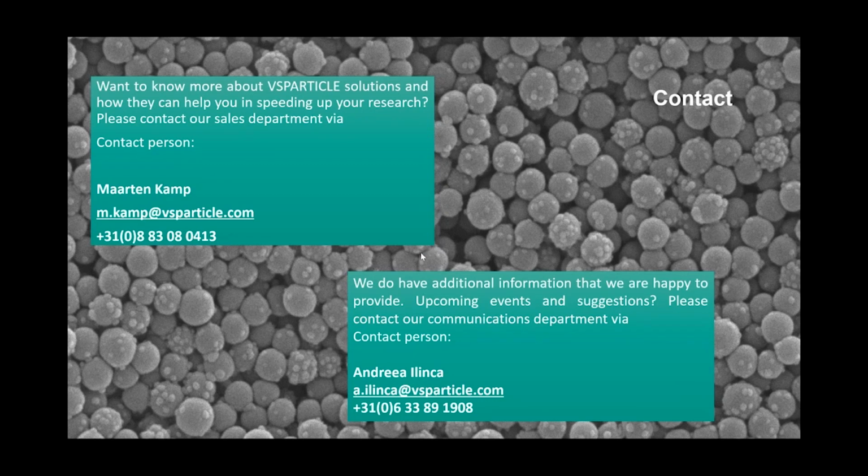Yeah. Someone asks if we could elaborate on sensors, especially how you contribute to sensor design. So at the moment we are primarily focusing on mass manufacturing of metal oxide gas sensors, and especially those that are MEMS-based. It's not that we are doing anything on MEMS design in that respect. It's primarily that we can print these nanoporous, highly porous layers locally on the heating chip or the heating membrane of a MEMS-based gas sensor. So it's a combination of locally printing pure nanoparticles, which have a higher sensitivity since there is no contamination on them, and the fact that we can mix a variety of different materials together, which gives you the possibility to improve selectivity. If you want more information in that respect, again, please contact us and we can elaborate in more detail on that topic.